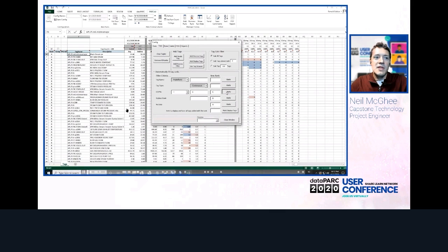Valve states may be something we want to keep track of, but we may want to keep them in a separate section. We know our valve tags end with .out or .valve, so we can change the rank of any tags with that in the tag name. Some state tags, like valve open, closed, or a pump running, not running, can be useful, especially because we are using hourly averages, but we may want to move them to a separate section as well.